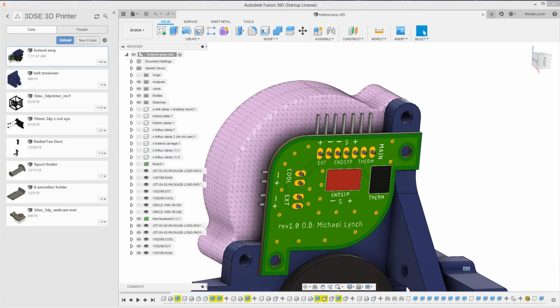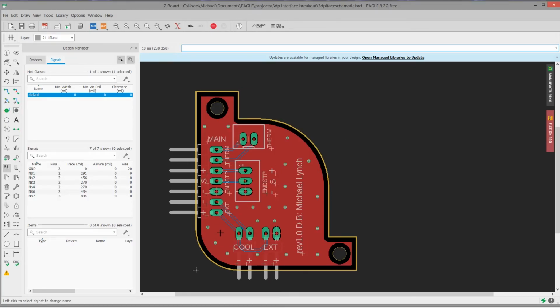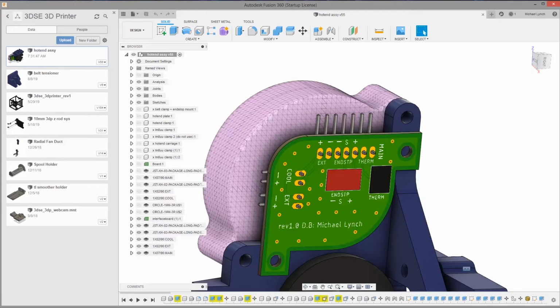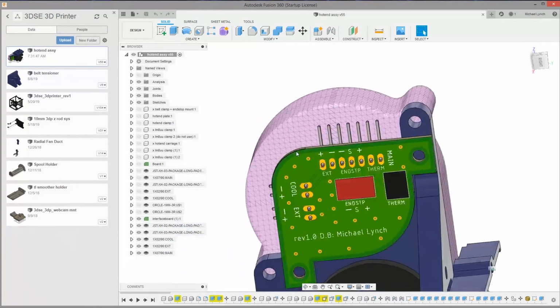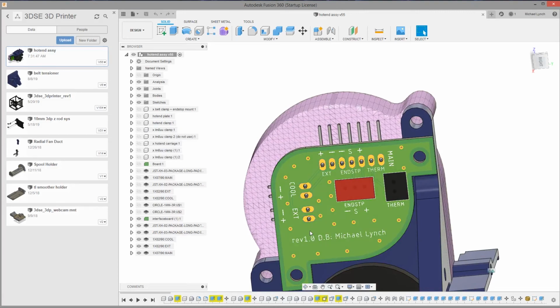Now, another common practice for the board design is we could put in some fiducial markings, which is another library I can import, but I don't really think it's necessary for this design because all of this stuff will be hand soldered on. It's not going to be machine soldered or anything like that. So I'm not going to worry about any sort of extra markings for a machine to identify. That's nothing I have to really worry about right now. I think I put it in the other board that I did, the previous design, but this one worked just fine.